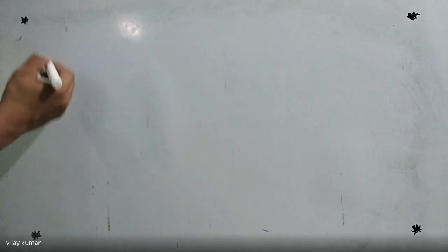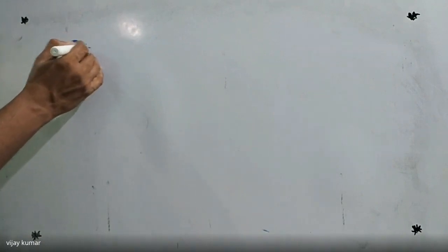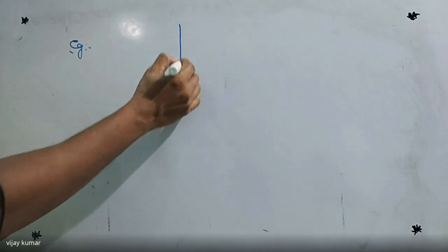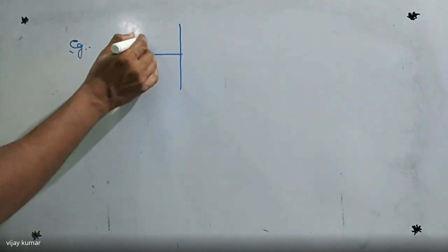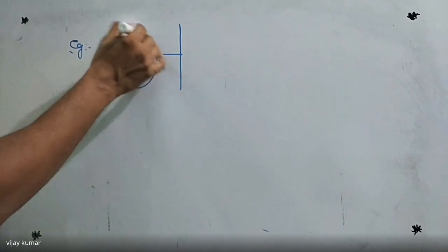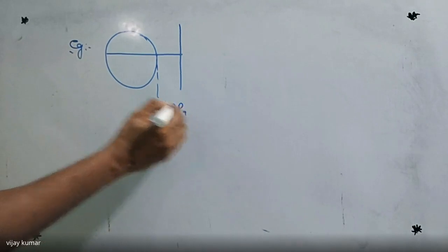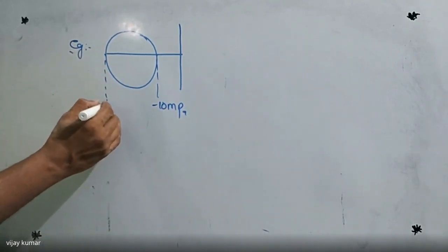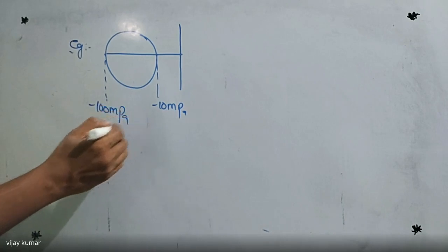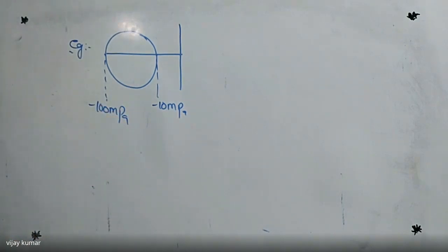Now, see this one here. So here they have given a question like this, an example question. This diagram is given, and this one is the Mohr circle diagram. This value is minus 10 megapascals, and here it is given minus 100 megapascals. So this is the given diagram in the GATE examination. Now tell me, anyone, what is the value of maximum shear and what is the radius of the Mohr circle? Both are the same, maximum shear and radius of the Mohr circle.